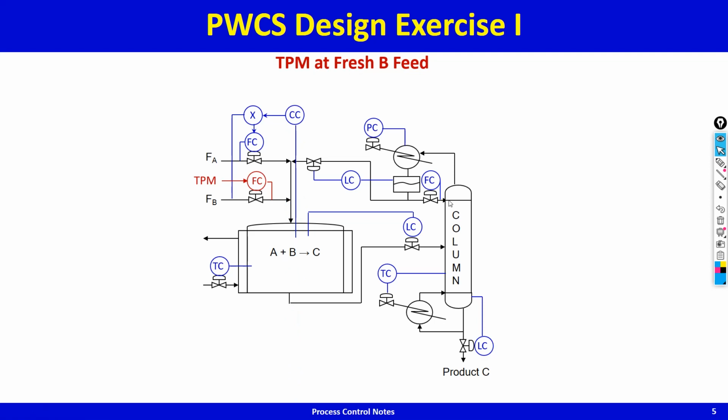It will reflect in whichever component is in excess, its composition building and the composition of the other reactant decreasing. So you hold the composition of a reactant in the reactor by adjusting the A to B reactant ratio, and with this you have no drifting modes. All balances, material and energy, are closed properly. This is a proper control system, a consistent control system that closes all balances.